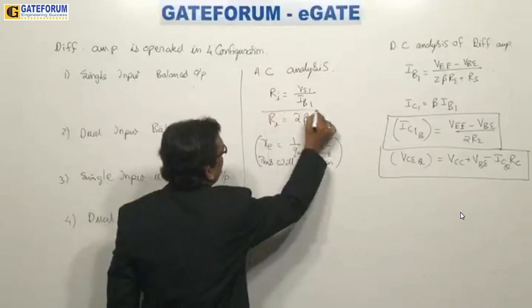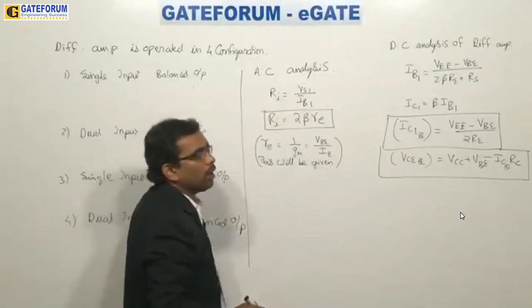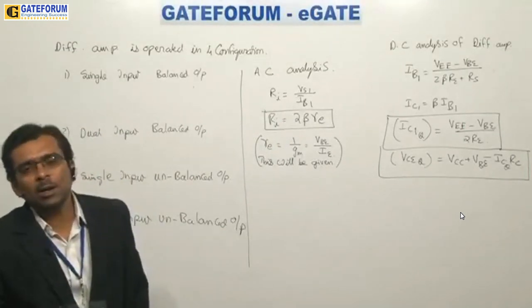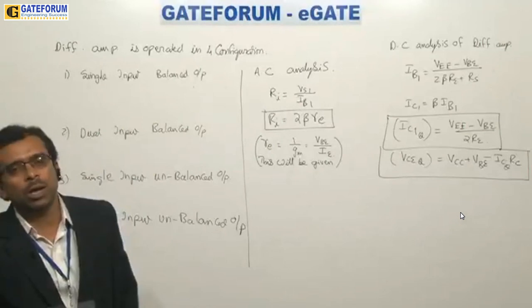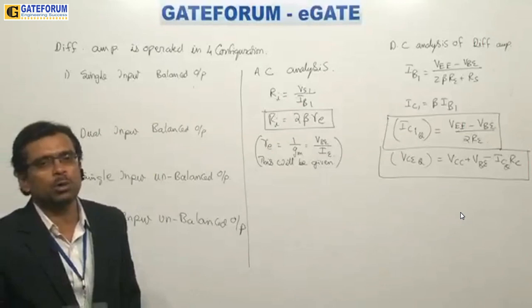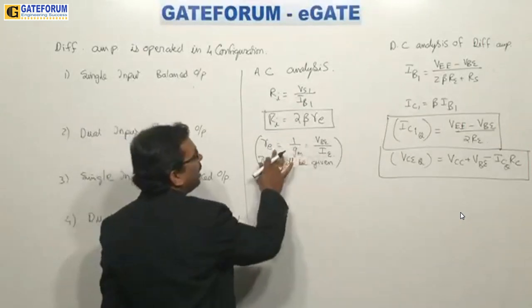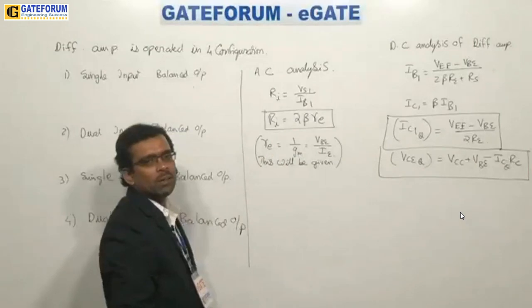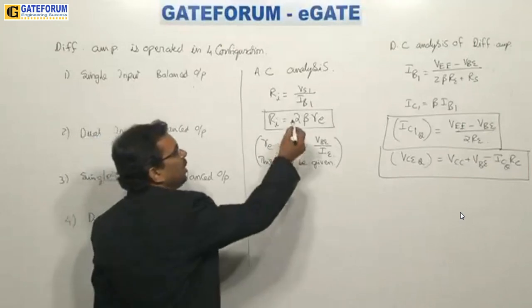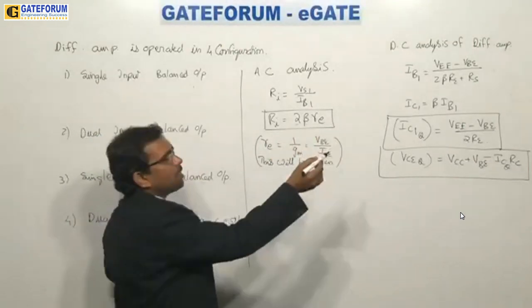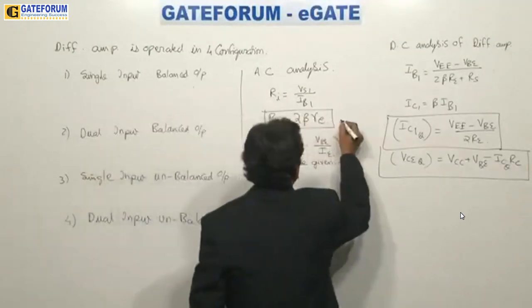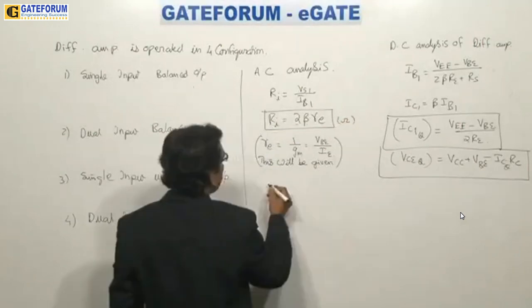Now you can see here, this is the formula, very important formula for the differential amplifier. When a differential amplifier is given to you, if you keep on writing KVL and doing all AC analysis, H parameter analysis, you will never get the answer. It will become 2 to 3 pages of information. In exam, you are not supposed to do like that. You need to remember that RE value will be given to you in the question itself. Just take the beta of that circuit and multiply it with this. That's it. Directly you are going to get the RI value here. Now, this is here, ohms.